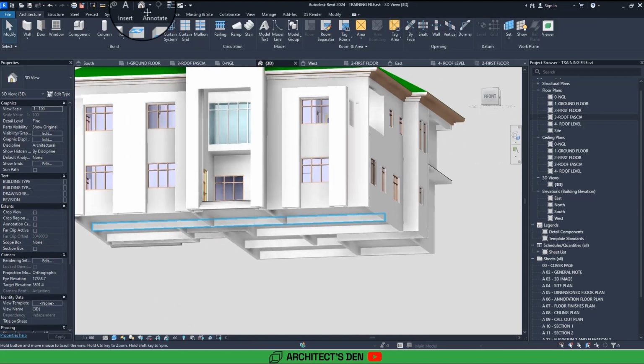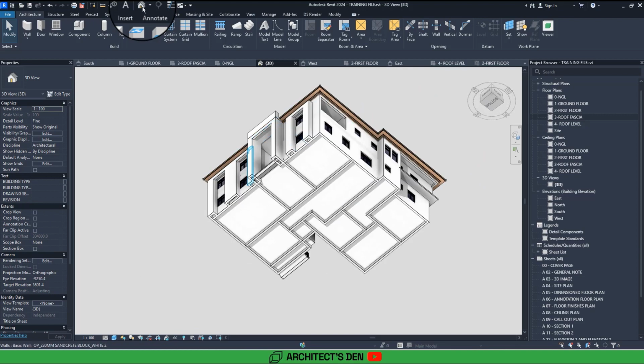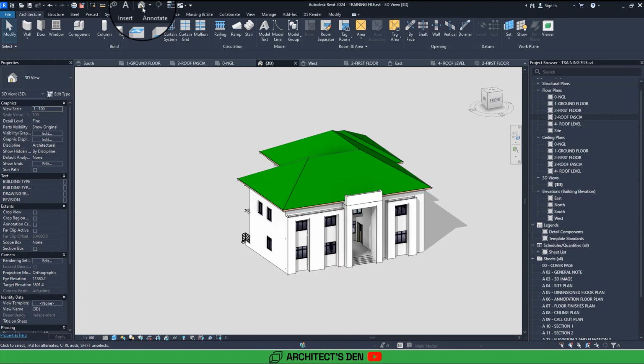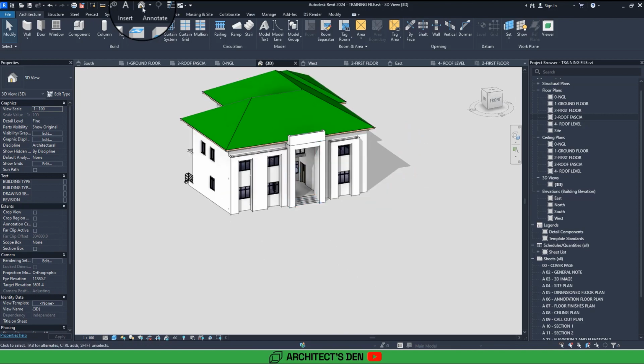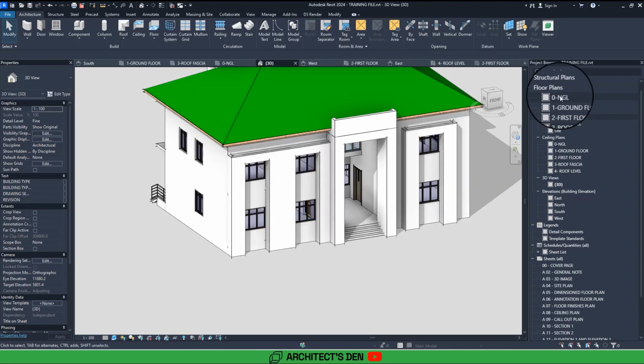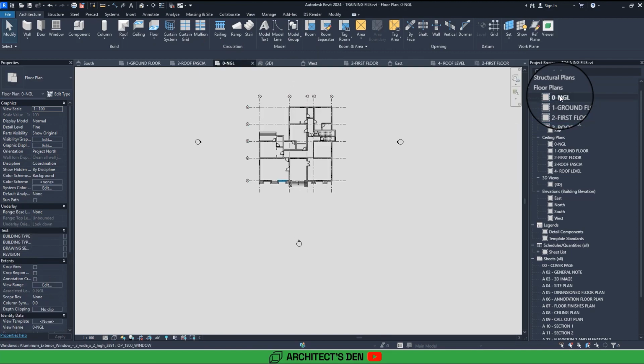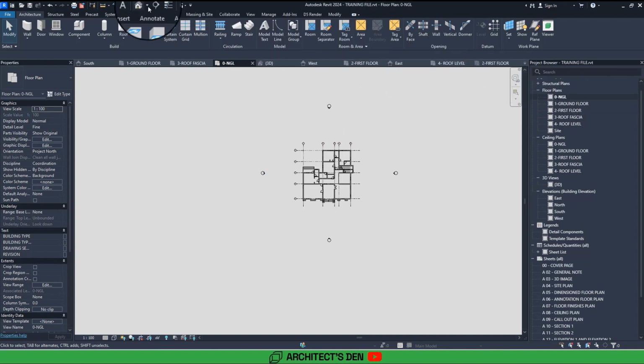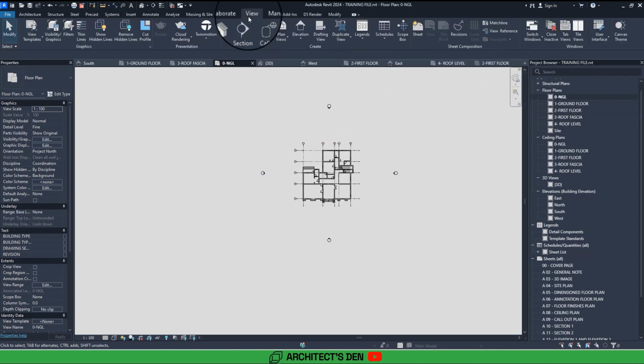So if you go underneath, you won't see any space through. Everything is covered, and so this is what I've been able to design. And for now, we can just go ahead and cut a 3D view to appreciate our work so far. So I'll go to the ground floor, natural ground level. Under this camera view, there are 2 ways to do it. You can click on view, and under view, click on this camera view down here, and you see camera. There is also a shortcut here on this icon, and the same thing, you can see the camera there.